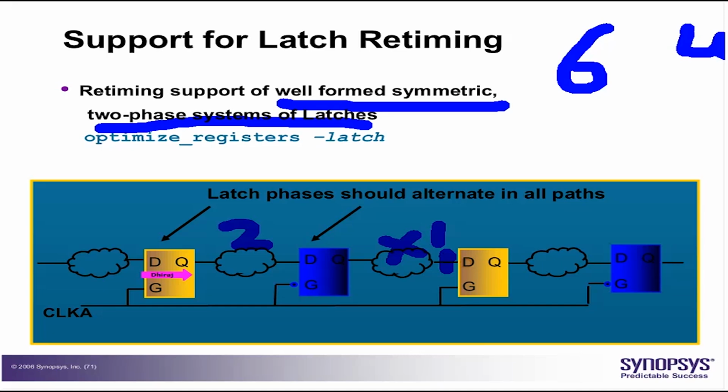Ideally, your RTL will not have this. It is not recommended to design with latches. They are used only in very special cases, for some very special circuits. So just keep this in mind that the support is available, and in most cases you will not encounter this. But we will see timing reports.